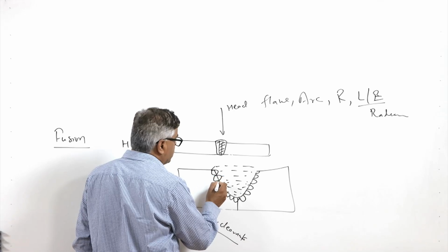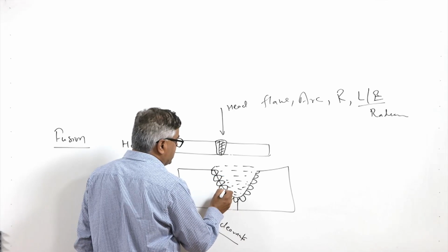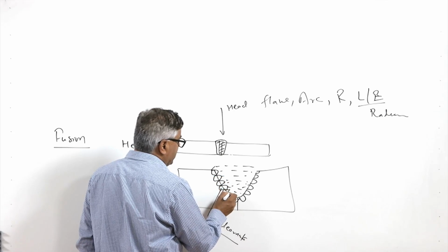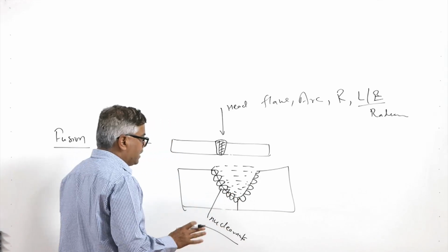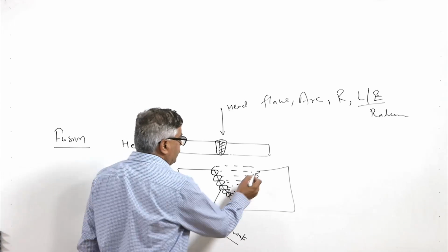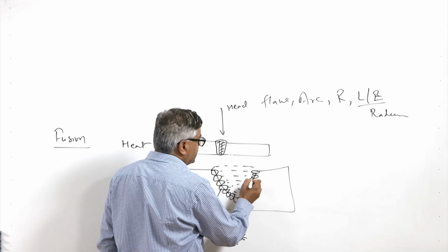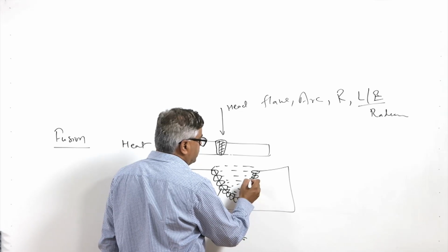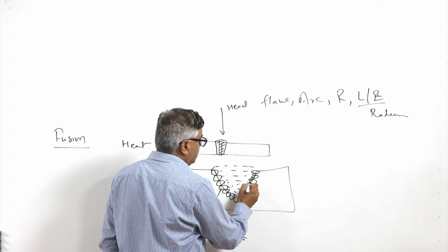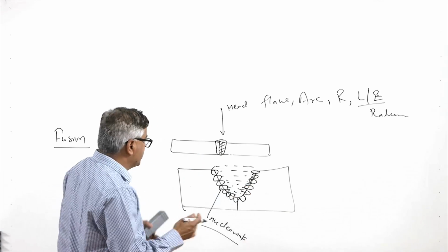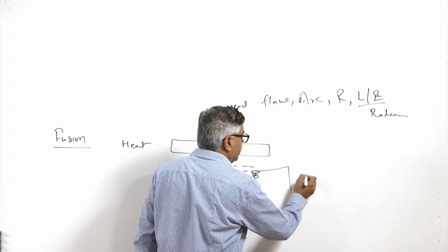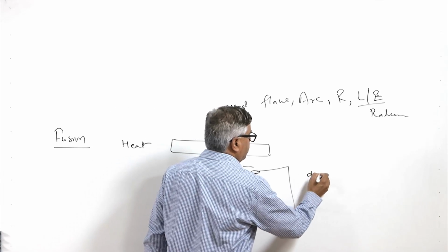In this case no nucleation is needed, because partially melted grains of the same composition are already present. So, where the base metal is just brought to the molten state, solidification occurs directly by the growth approach.